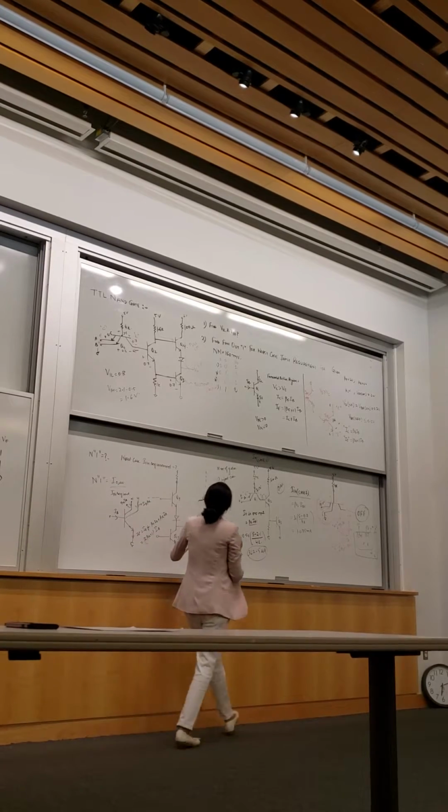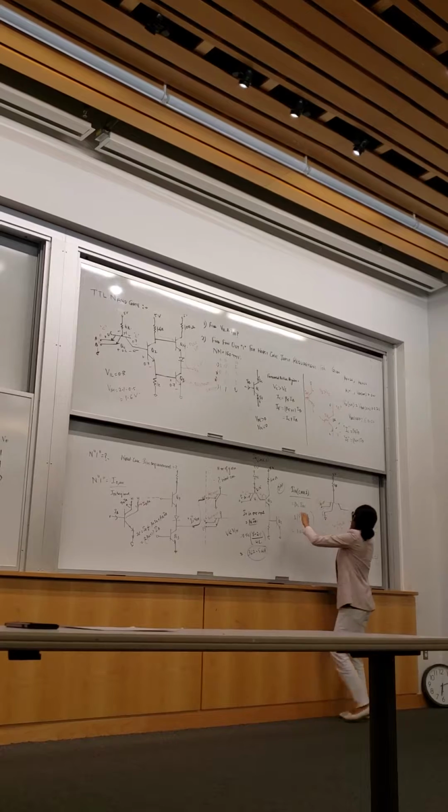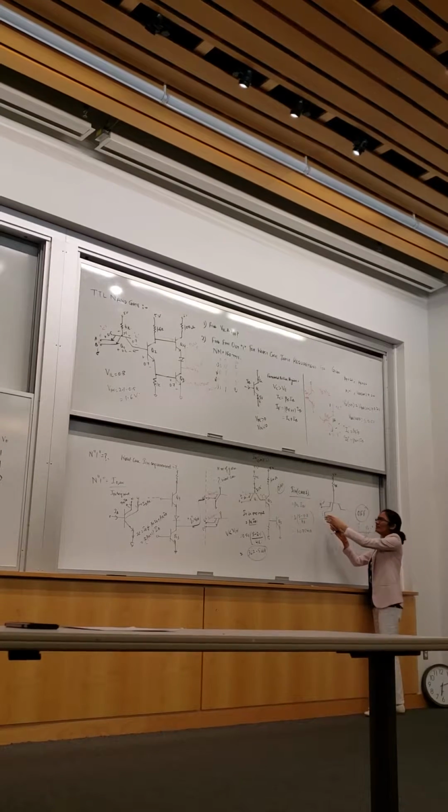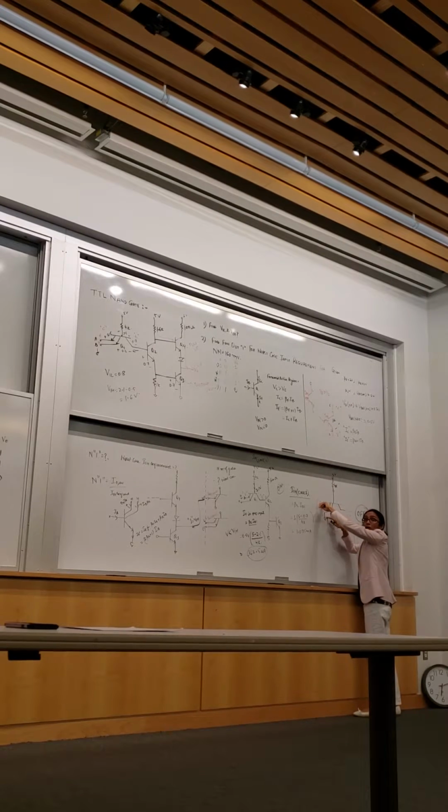Yeah. So if you set both of these low, like for example here, all of the current is going to flow here, right? All of the current is going to flow here, this is off. So if both junctions are on, this current is going to get divided into two branches, because they're acting as a diode, base emitter diode.